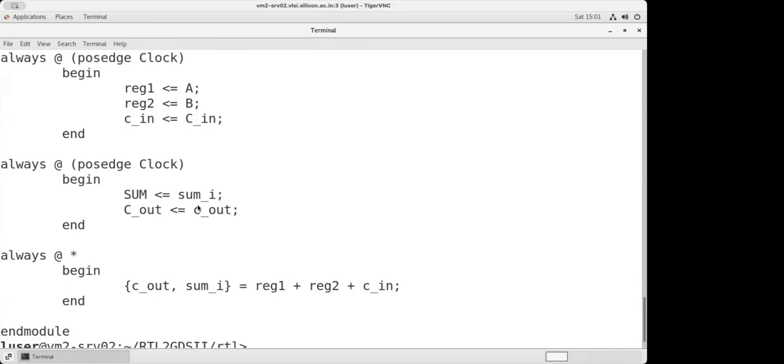What you can do later on, maybe after today, is go back and similarly try a subtractor, or a bigger adder. In place of 4-bit, you can go with an 8-bit adder also. In whatever way you can write an RTL, write a combinational RTL, and on the input and output, just apply the flip-flops. It becomes an industry-specific design. Okay, now let's do the simulation, translation, whatever is to be done.